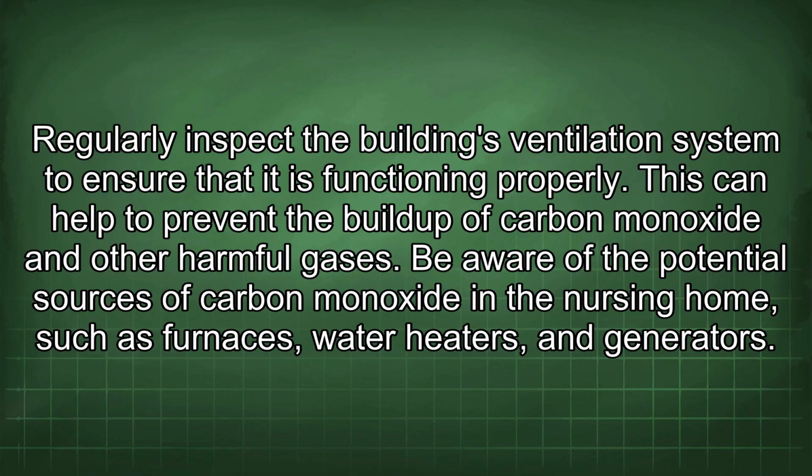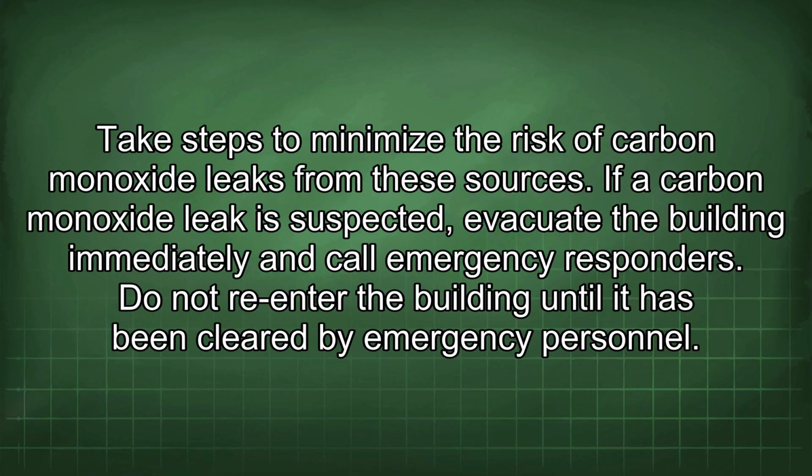Be aware of the potential sources of carbon monoxide in the nursing home, such as furnaces, water heaters, and generators. Take steps to minimize the risk of carbon monoxide leaks from these sources. If a carbon monoxide leak is suspected, evacuate the building immediately and call emergency responders. Do not re-enter the building until it has been cleared by emergency personnel.